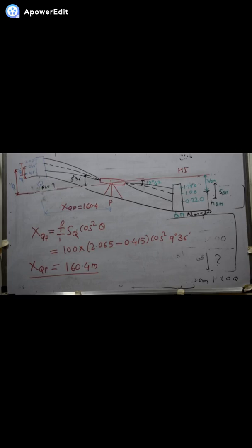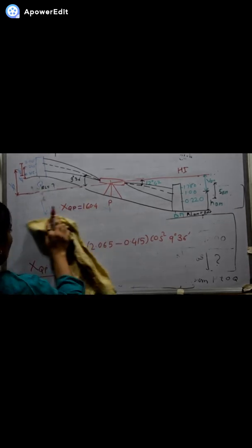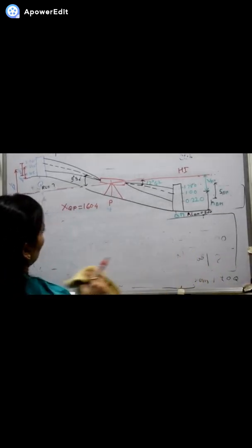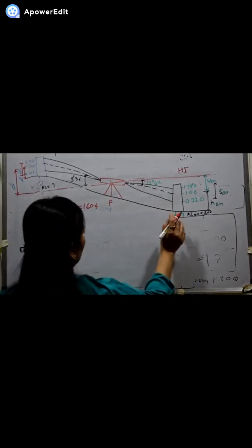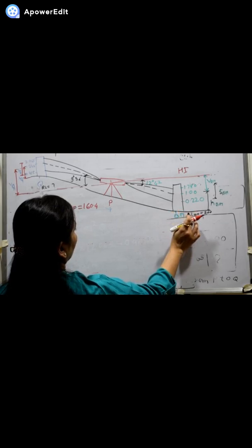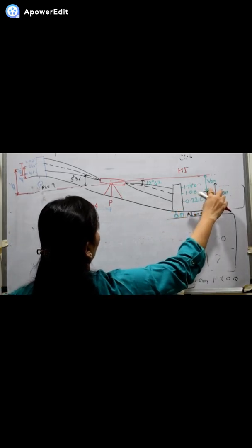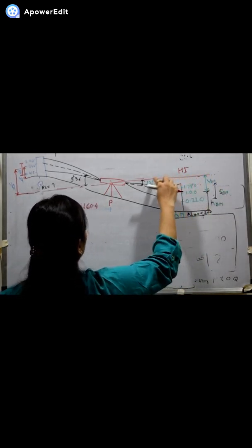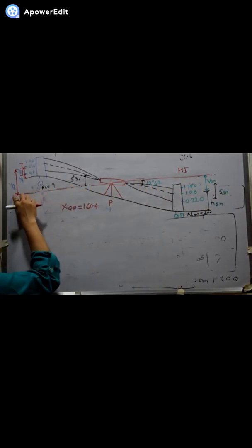Now we have to calculate the RL of Q. To calculate the RL of Q, first we have to calculate the vertical distance. Now if you say this is like a puzzle, we know this height, isn't it? Then to this RL we will add the HB, the middle hair reading, then we will add the VB. This will give me the height of instrument.